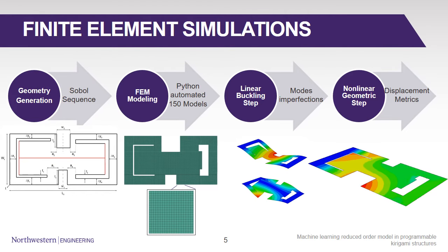So the first stage was to do some finite element simulations. We generated the geometry by means of Sobol sequences to generate pseudo-random sets of geometrical features of the geometry. Then we automated the process of creating these finite element models for more than 150 models.